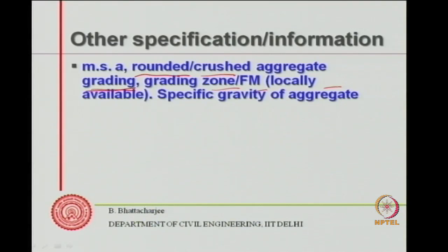So one would like to use locally available aggregate, and therefore what are the size fractions available? If there is anything missing, such informations would become important in mix design. But we have already seen how the maximum size of aggregate affects the packing characteristics, how shape of aggregate affects the packing characteristics, and its effect on fresh concrete, etc. We'll understand, of course, later on.